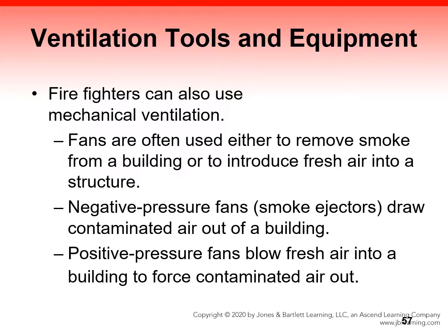Firefighters can also use mechanical ventilation. Fans are often used either to remove smoke from a building or to introduce fresh air into a structure. Negative pressure fans, or smoke ejectors, draw contaminated air out of a building. Positive pressure fans blow fresh air into a building to force contaminated air out of the building.